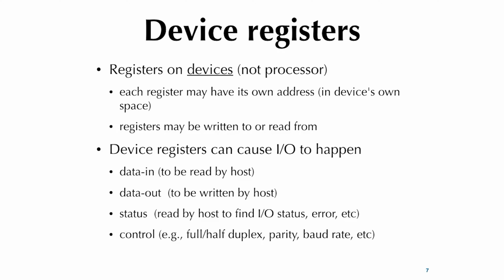So in the case of 8051, you do have some special function registers or SFRs that are really for the built-in devices. For example, your UART is considered a built-in device, even though you can think of it as part of your instruction set. Still, logically speaking, it's an external device that happens to be accessible from the processor. But most other things, if you do an LCD controller, you do a hard drive, well, there are registers associated with each one of these devices, not in the CPU space, but in the device space.